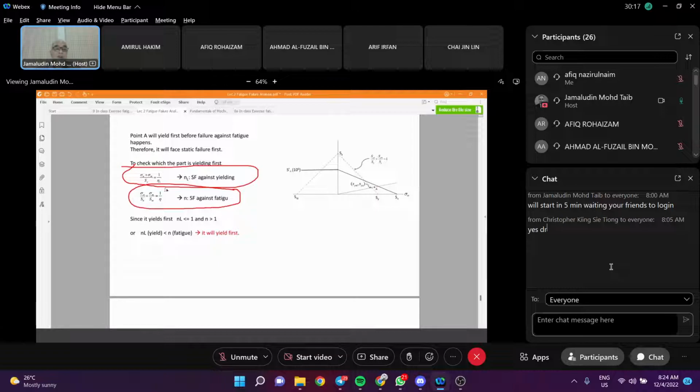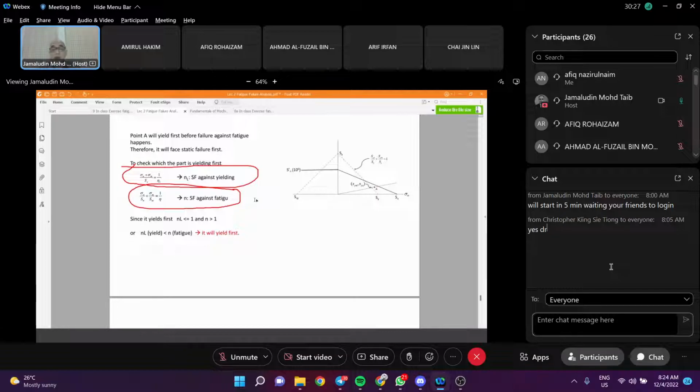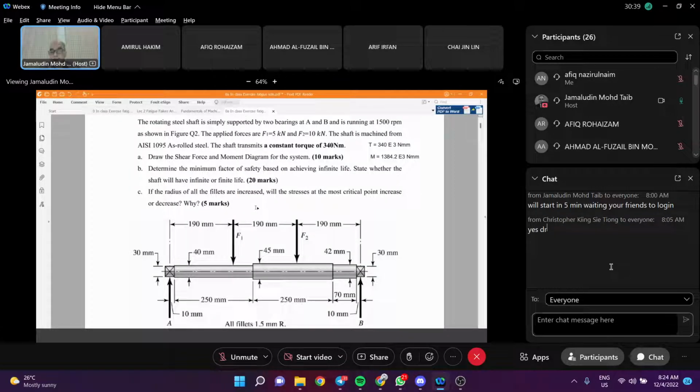Okay, the second value here, we call Goodman. Remember the Goodman diagram, the safety factor. If the safety factor is larger or equal to 1, it is going to be infinite life, and the value will be there. All right. What we should do is remember the 3 important parts, what I call finding the KF, SN, and determining whether it's going to be mean or alternating. Okay, right. That's the first step now.